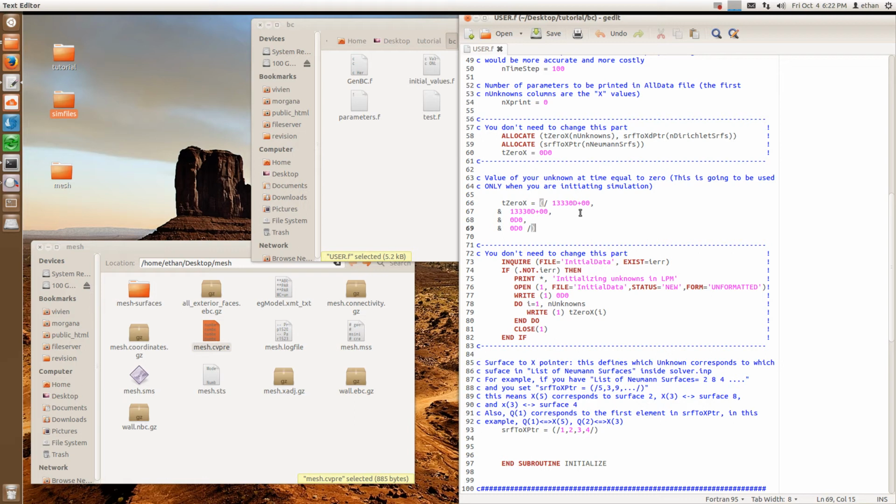So since we're prescribing a pressure boundary condition, then we're setting values of the pressure. And so this just tells the computer, at time step 0, when it hasn't solved anything yet, it needs some number to begin with. So this is just a guess that you're entering, so that you're able to actually kick off the simulation.